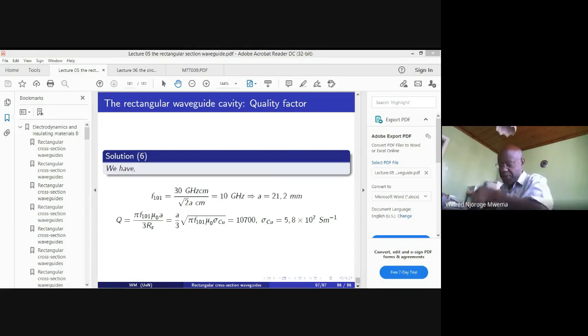Can you give a guess of what you would expect the signal to be like? So the antennas usually, depending on how you are looking at them, an antenna being a very small kind of device or structure, we can assume that the waves leaving the antenna at that particular time would be spherical TEM waves. That is, they are almost like plane waves, but since we are nearer the source, they'll be radiating out in a spherical kind of space. Okay? It's like coming from a point and being radiated out.